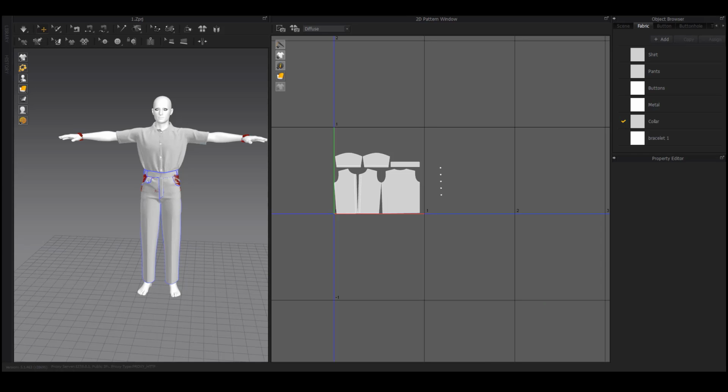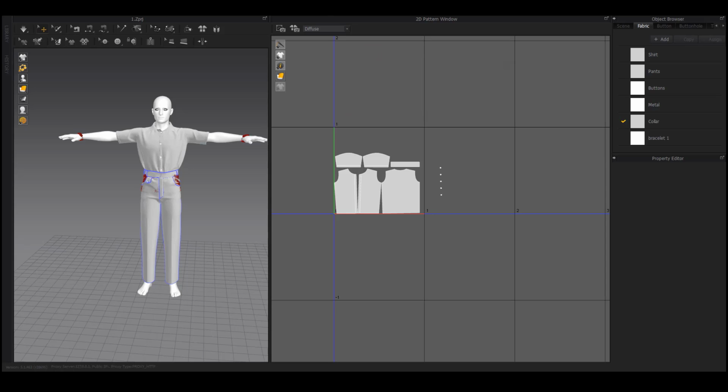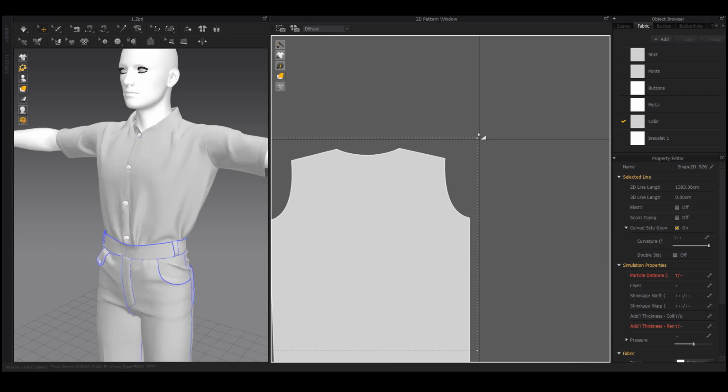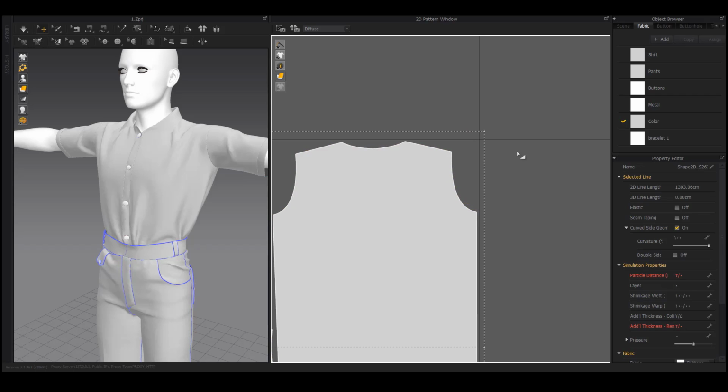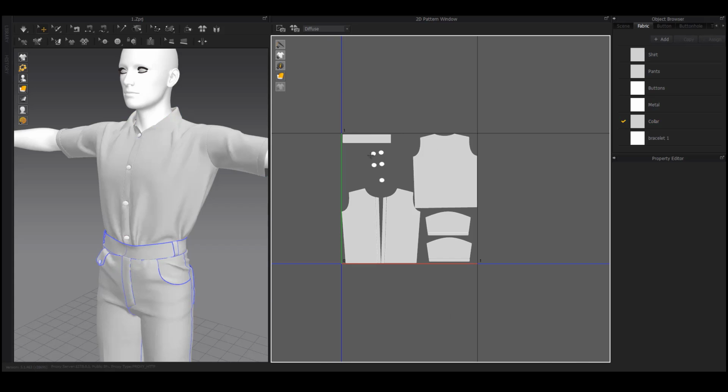The current topology of the model is triangular. The correct topology for other software is quadrilateral, and for the model to be standard, it is better to make the model topology quadrilateral. In the first case, you can select the model and select the quadrangulate option, in the 3D garment section, in the Edit and Context menu. This command allows the irregular topology to become quadrilateral.